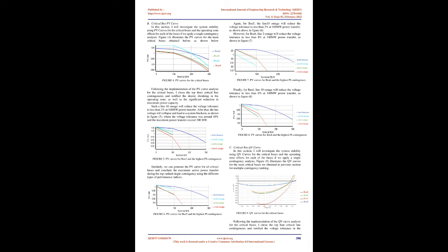After building the system and obtaining the base case result for the lines and buses, I performed the contingency analysis using DC and AC power flow analysis in the PowerWorld simulator under the single line outage scenario. The simulator reports that the DC power flow has a total runtime to complete the contingency analysis of 0.21 seconds, compared to 0.35 seconds for AC power flow, as shown in Figure 1 below.